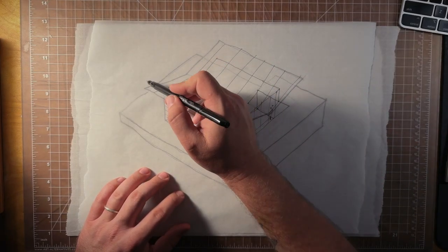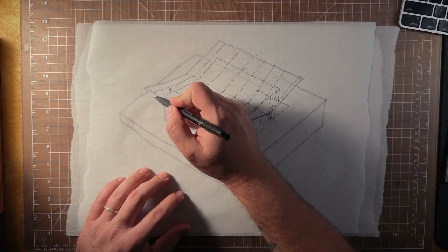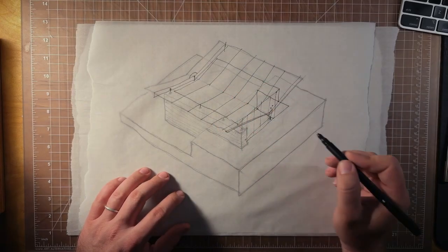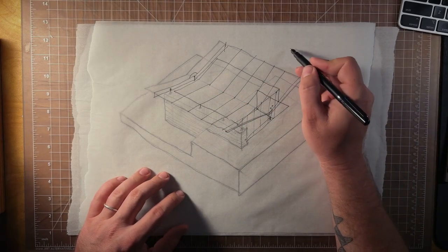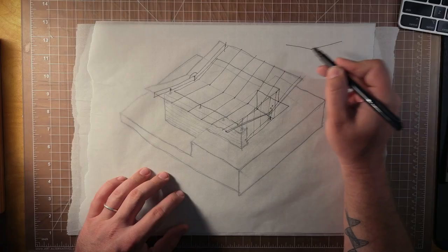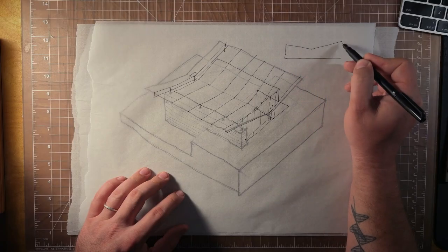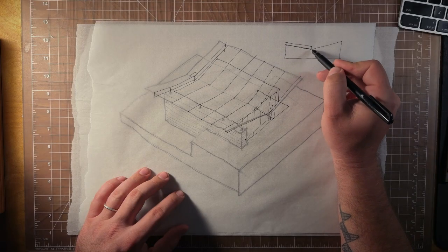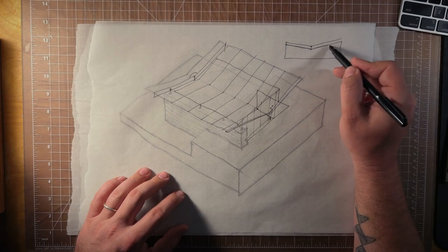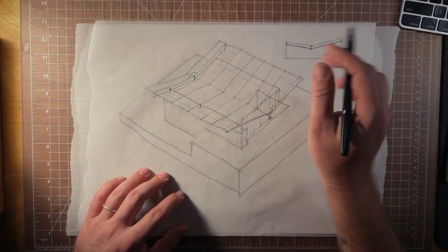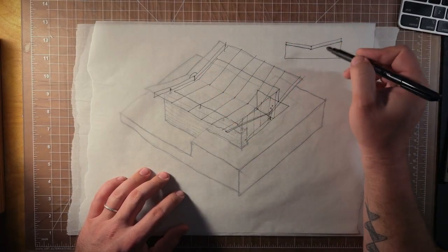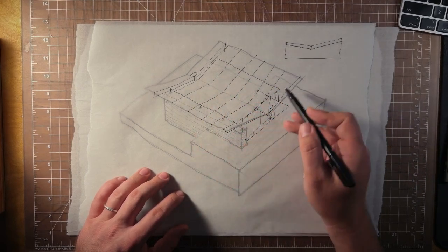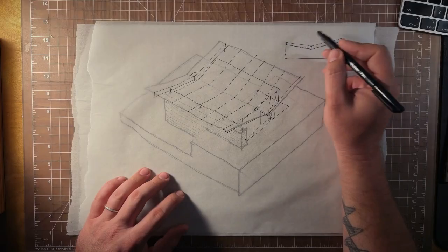For example, a jig is something that would help me glue wood members together at this exact angle, right? Repeatedly. So the jig would look something like this as a solid piece, and I'll show this a bit later in this process, and that would allow me a place to lay in and glue wood members that then, once they're dry, I could take out of this kind of mold and repeat the process and lay in wood in there again and glue it, and have a series of, for lack of a better term, glulam beams, or maybe even trusses. You could build something like this to invent a truss.